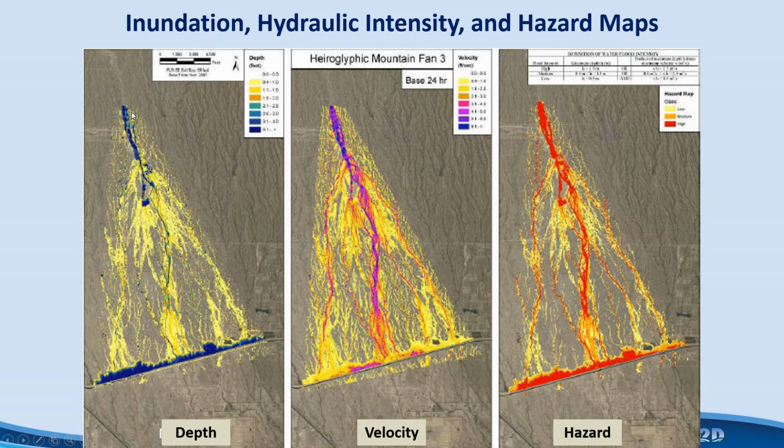So this depicts these. If you have an alluvial fan, you might have flow depth, velocity, this is hydraulic intensity, and then you generate the hazard map from this plus the different return periods, or for a given event. This would be a hazard either for, like, say, the 20, 100, and 250-year event, or the 5, 10, and 50-year event, or something. You could generate this as a function of frequency, or generate this hazard map for just a given event, say the 100-year event or whatever your design event might be, and associate it in that manner.